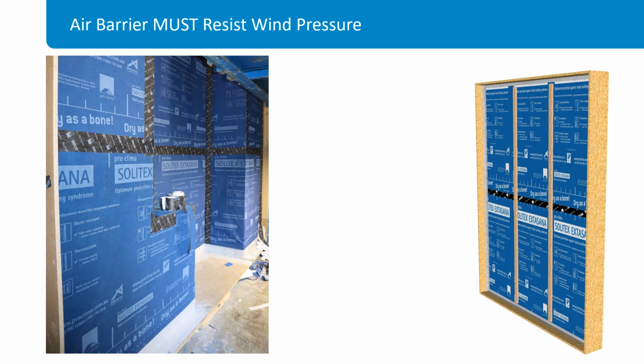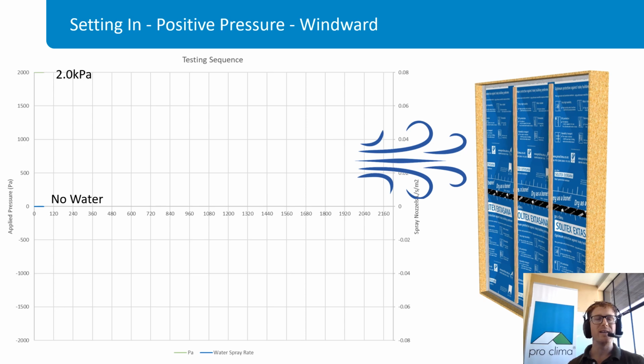So when we go through that full-scale facade test under AS 4284, the first thing you do is put the design wind pressure straight onto the facade and try to force the weather-resistant barrier into deflection, essentially stressing the seals on the weather-resistant barrier system. So in this case, if it was a 2 kilopascal design pressure or serviceability limit you're designing for, you would put 2 kilopascals of pressure onto that facade.